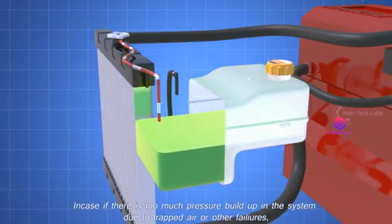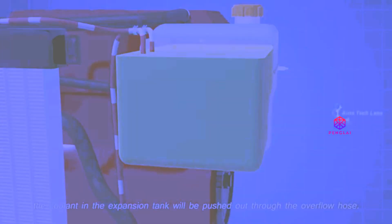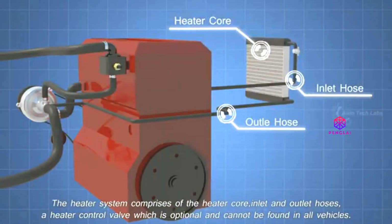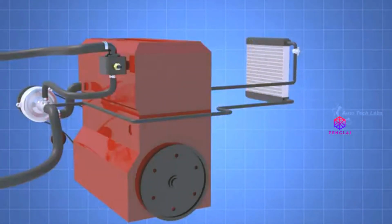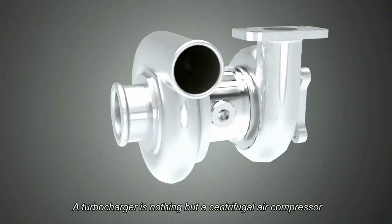In case there is too much pressure build-up in the system, due to trapped air, or other failures, the coolant in the expansion tank will be pushed out through the overflow hose. The car heater system is a part of the engine cooling system. The heater system comprises of the heater core, inlet and outlet hoses, a heater control valve which is optional and cannot be found in all vehicles. The heater core acts as a radiator, dissipating heat from the hot coolant to the vehicle interior.